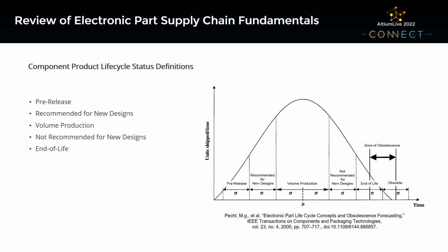The manufacturer should be contacted to assess any available opportunities to make, say, a last time buy purchase, and to review the time periods for placing final orders and receiving final shipments. Authorized distributors will typically continue to sell the component until the stock is exhausted. It's not uncommon to see this in our supply chain information within Altium Designer in an ActiveBOM, and you'll see that there's an end-of-life component, but there's still plenty of stock available.